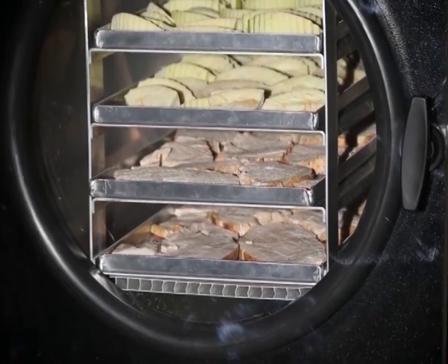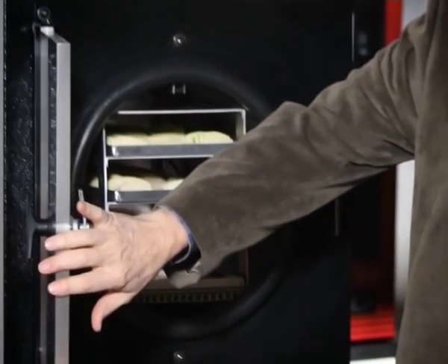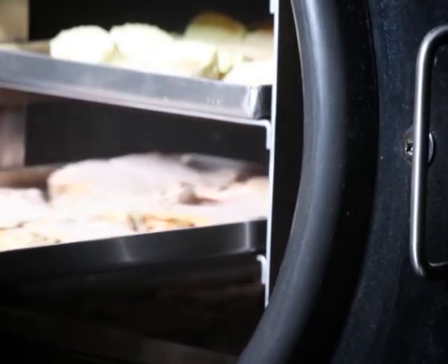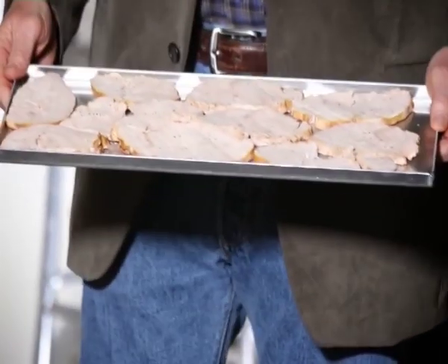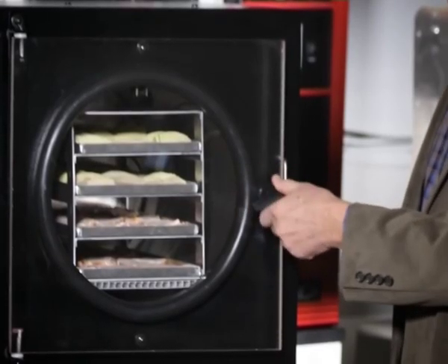Once the free moisture is evaporated or completely removed by drying, the diffusion rate to the surface significantly reduces, since bound moisture comes out very slowly. As a result, the drying rate falls gradually. This is called falling rate period of drying. The moisture content at which this change occurs, that is, the transition from constant rate to falling rate period, is called critical moisture content, MC.